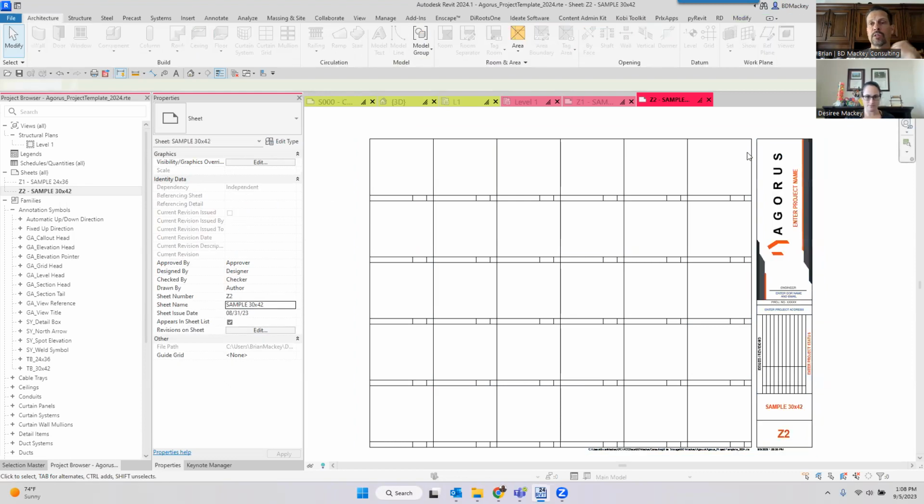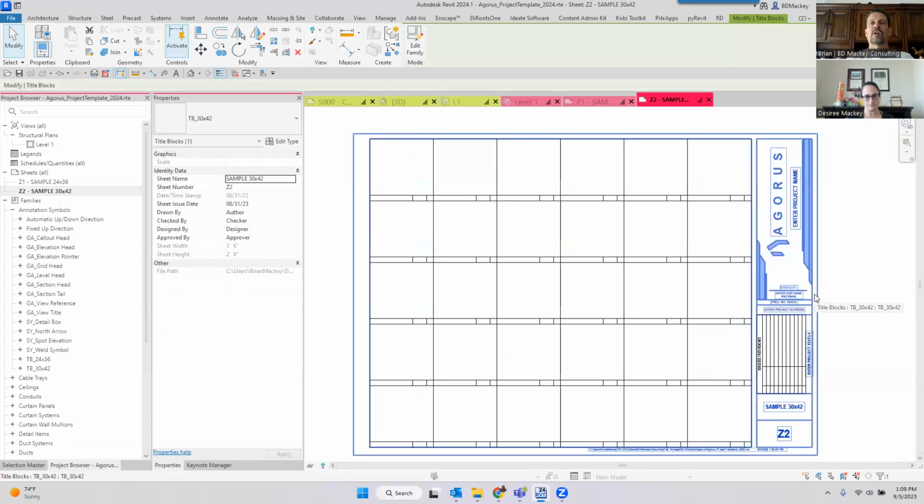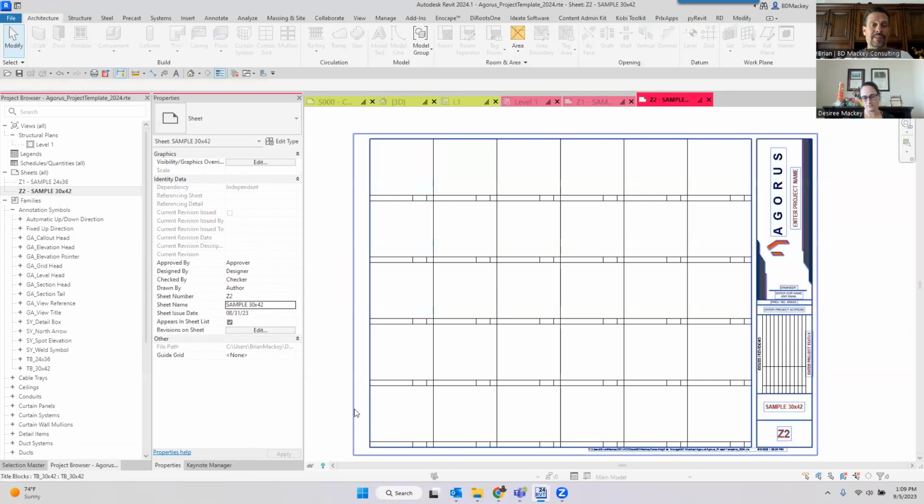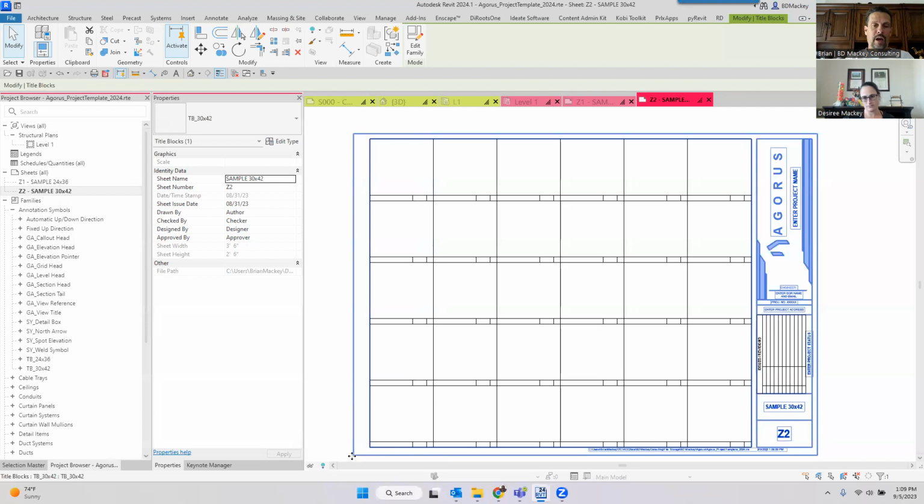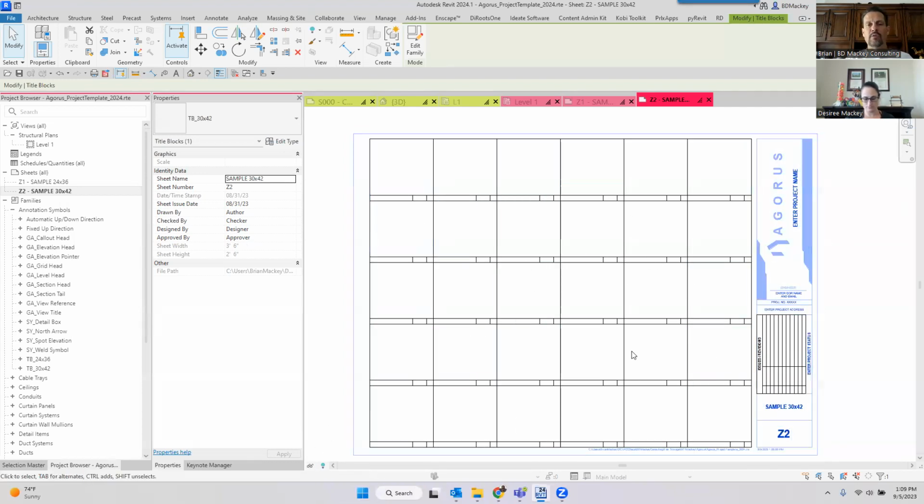I thought this was a pretty brilliant idea. I'd never seen anybody do this. If your title block's insertion point is right here, no matter what you're doing, the detail guides don't change as you change the setups for all the title blocks. I have a lot of clients, we've done the same thing, and myself included. The insertion point out of the box is the lower left corner, and we mimicked it. Then if you change titles, view titles or whatever, you're constantly moving them around.